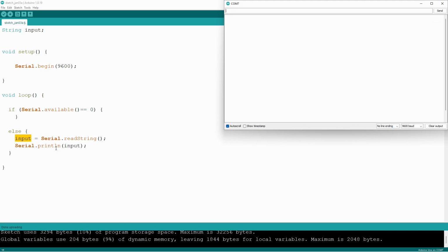To put this into practice, obviously before starting, you want to make sure that your baud rate is the same. If you choose both NL and CL, there will be gaps in between your sentences or your string if you wait too long. If you do not want this, just click on no line ending.